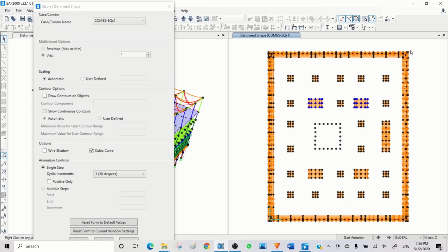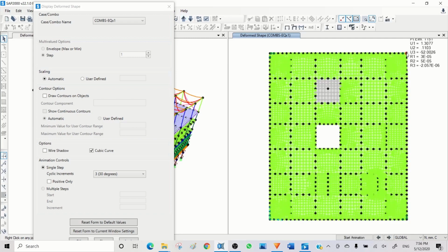so this is the foundation. Even here you may have a little bit of movement. The reason is the spring stiffness you have. You don't have a rigid stiffness. You see you have 1.3 millimeter of lateral movement here. Then coming to this level, it gives you 1.3. That means the walls are very stiff. The movement at the foundation level was due to lateral spring stiffness, but here it is a combination of lateral spring stiffness and the wall stiffness. Because the wall is very stiff, it doesn't really allow any movement. So you see the same number, 1.3 and 1.22, so a little bit of movement on one side.